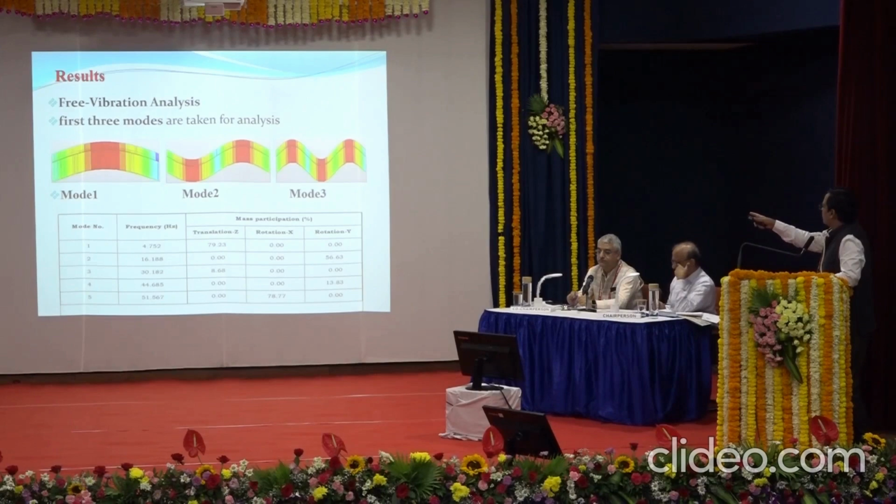The percentage of participation is 80% in the case of mode 1 for translation in the Z axis. And for rotation, it is mode 2, with rotation about the Y axis being 56.63 percent by mode 2.